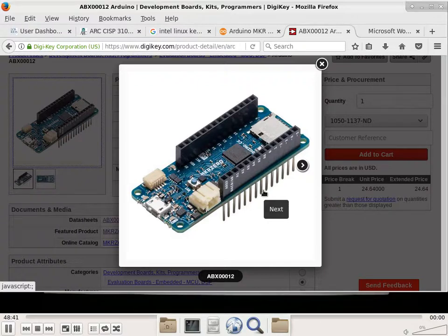So you have to take the accelerometer reading and then do the cross product stuff with the magnetic flux in order to find out the true heading direction of the chip. And then you store that into a variable with an object so that when the API is called, you're just pulling a number that is already pre-computed.